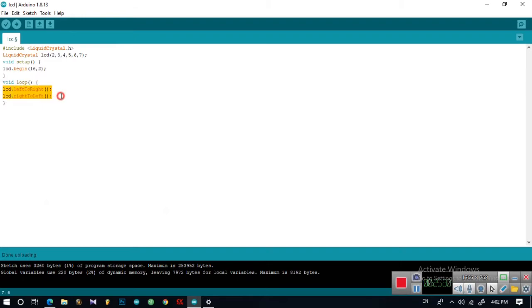And the next thing, the most important command, and also the last command, is when we want to create a custom character which can be used for creating graphics, shapes, and anything, stickers. So what we write is lcd.createChar, and the format is num and data.